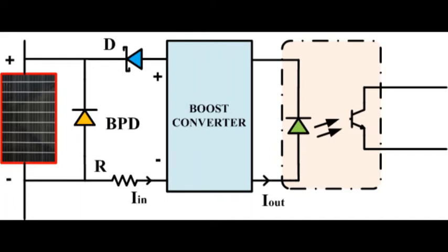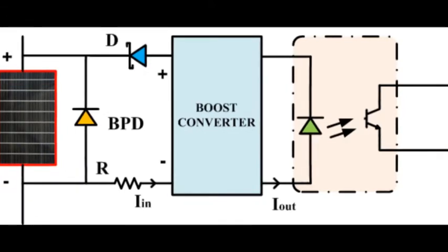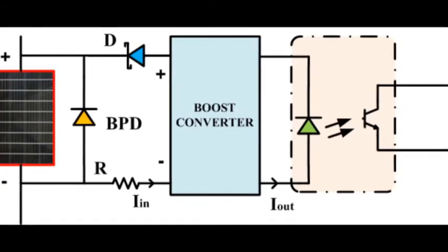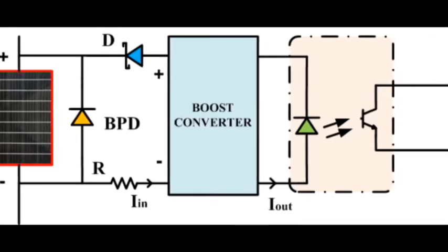The proposed scheme involves the principle of the detection circuitry being powered by the forward voltage developed across the bypass diode or BPD. When there is a fault, the bypass diode is forward biased and there is a voltage developed across the terminals of the bypass diode.